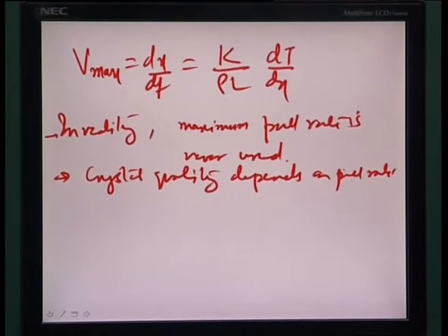So, you really cannot go very high in terms of pull rate, otherwise there would be a set of point defects which can quickly escape and go into the solid material. However, too much gradient may also create large thermal stresses and thus dislocations, particularly in large diameter wafers. So, in a nutshell, it is really the optimum best, which can be derived experimentally, as to what the pull rate would be in real terms.